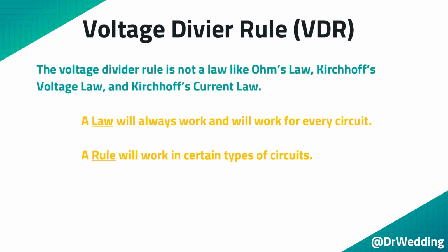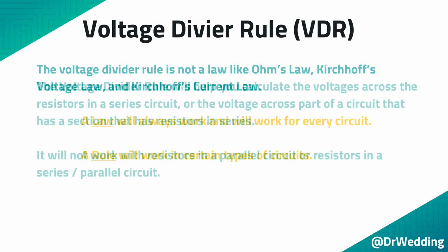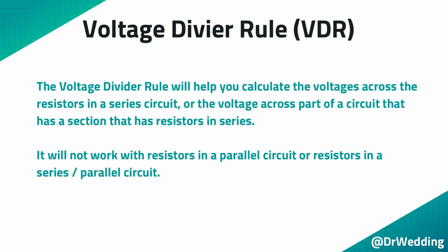The voltage divider rule is not a law like Ohm's law, Kirchhoff's voltage law, and Kirchhoff's current law. A law will always work and will work for every circuit. A rule will work in certain types of circuits. The voltage divider rule will help you calculate the voltages across the resistors in a series circuit, or the voltage across part of a circuit that has a section that has resistors in series. It will not work with resistors in a parallel circuit or resistors in a series parallel circuit.